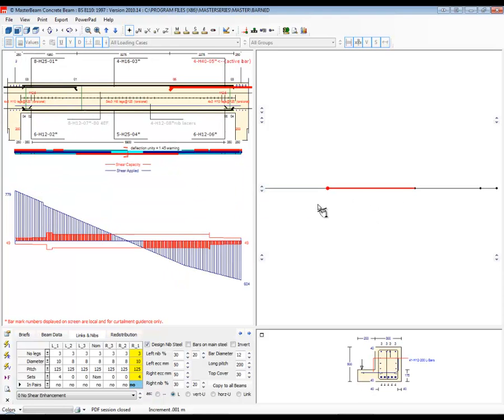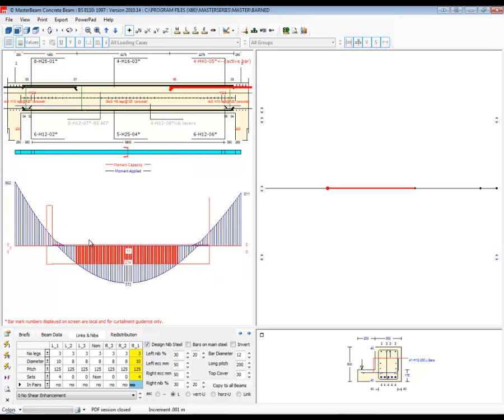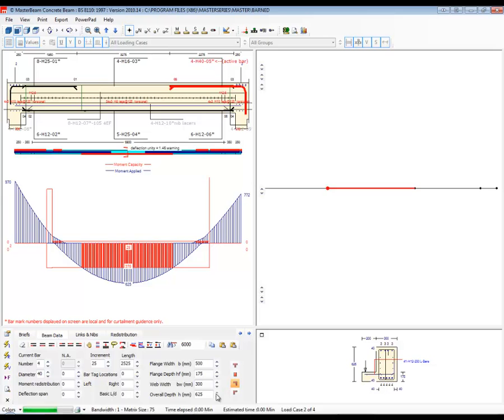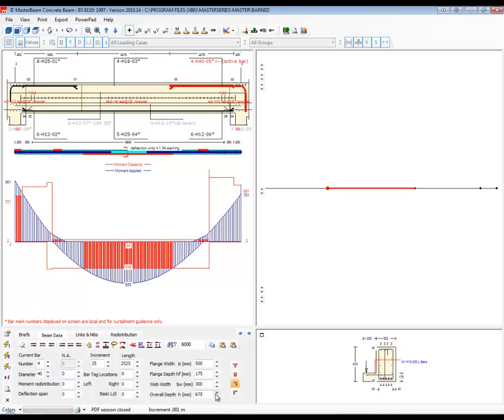Now, this is where we end up having awful problems in shear and bending, because really the section is not meaty enough to work. And this is one of the nice things about the concrete design. You can change your section sizes and see what the effect is. So I can say, well, actually, if I made that, say, 600 overall depth, will that help? And it's beginning to help, but not totally, because of the problem with the torsion. What's happening is this load is pushing the whole beam and causing it to twist and torsion.